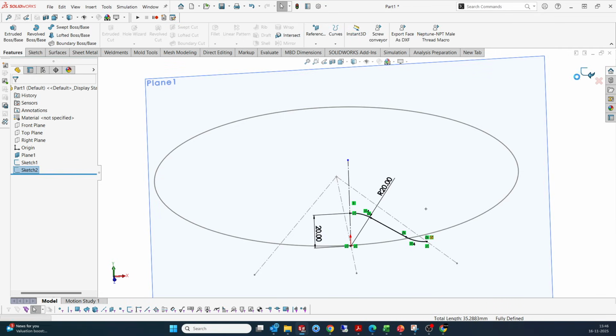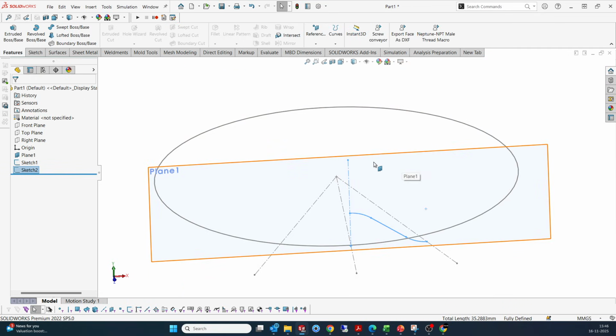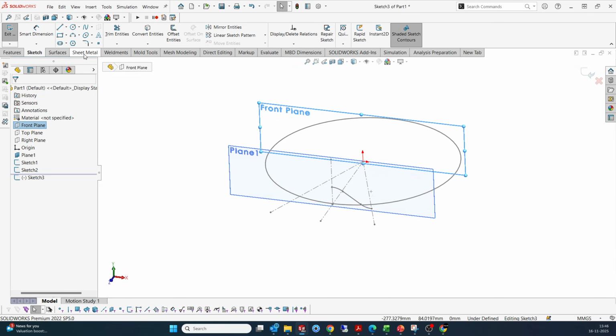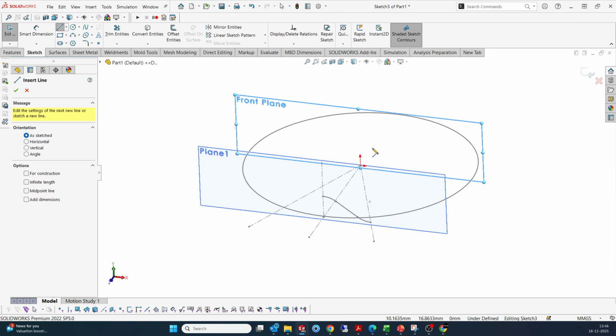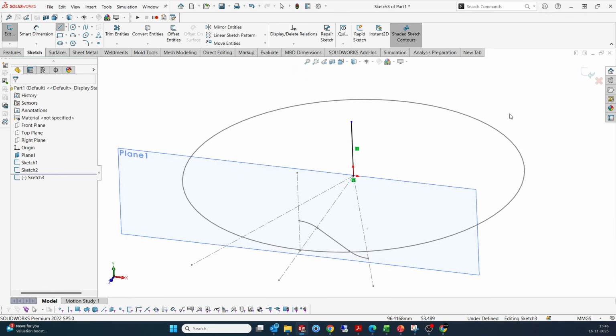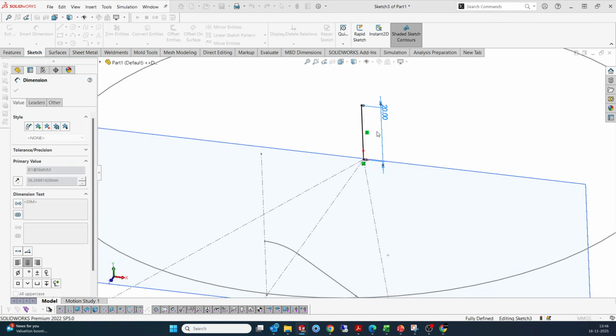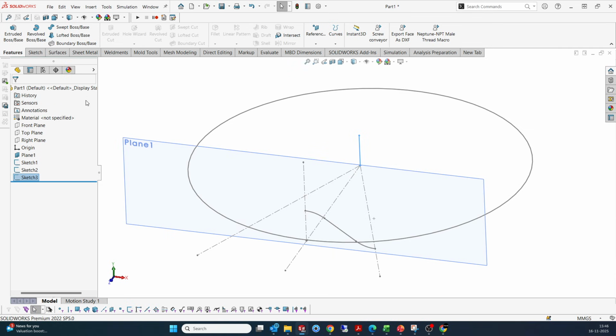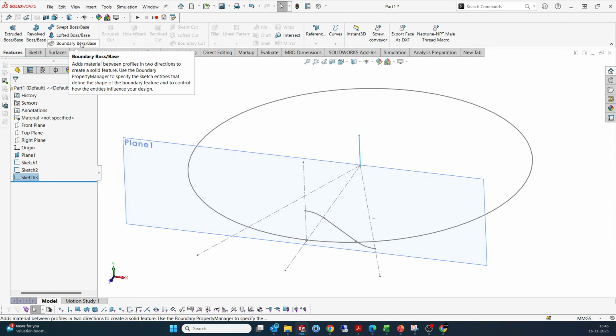Okay, so my side profile is ready. Similarly, the other profile also has to be created. So I have to select the front plane at this moment, select a line and then go for a center, and I'm gonna select this. This time again, I'm gonna create a 20, so that the heights match each other, which I want to maintain. This depends on you. If you want more height, you can just extend that and try it out, maybe one smaller, one bigger, like a different profile again.